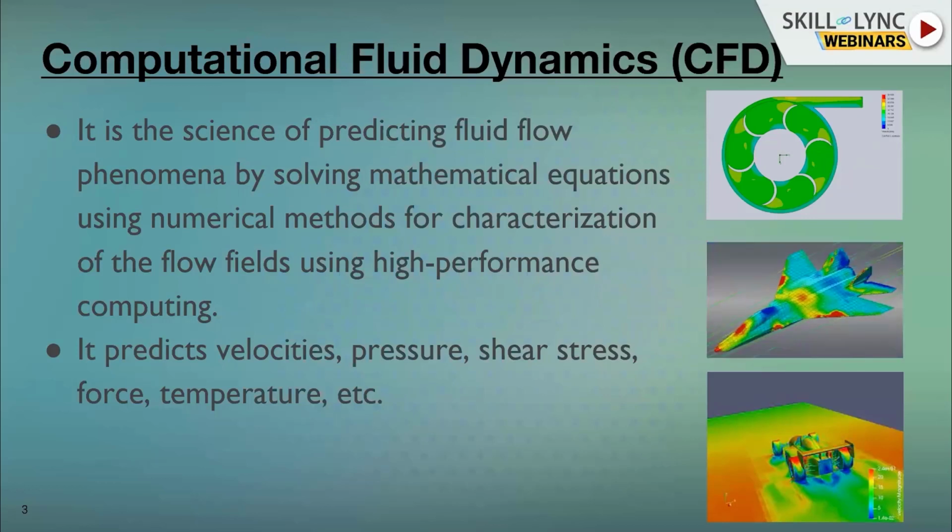But you might have studied in your curriculum that for simplified problems like flow through a circular pipe or flow between two fixed parallel plates, using the initial and boundary conditions, you can simplify the Navier-Stokes equation and obtain solutions for velocity profile, flow rate, or pressure drop, etc. So there are certain problems we can simplify and find exact solutions. But in most cases, in reality, many engineering applications, including fluid flow, are complex and cannot be simplified and solved like that.